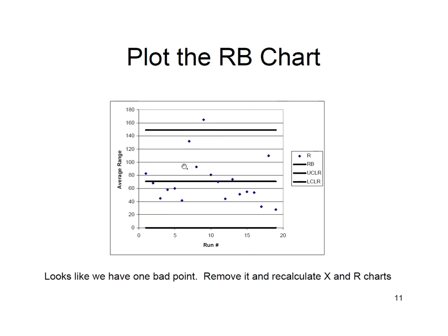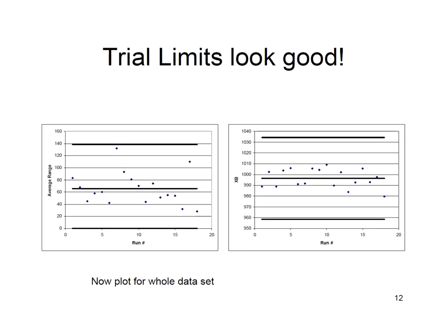And the same, now we have the range, right, which is like the standard deviation. It has its upper and lower control limits and the average of the range. And you would just look at these points to tell you whether it's in control or not. So those are like the trial limits, meaning we only used so much data to create our control charts.